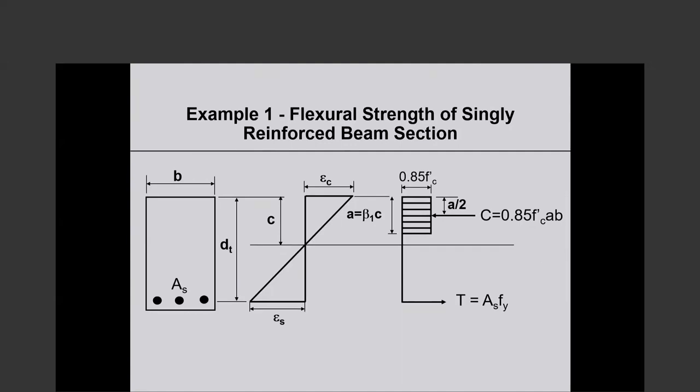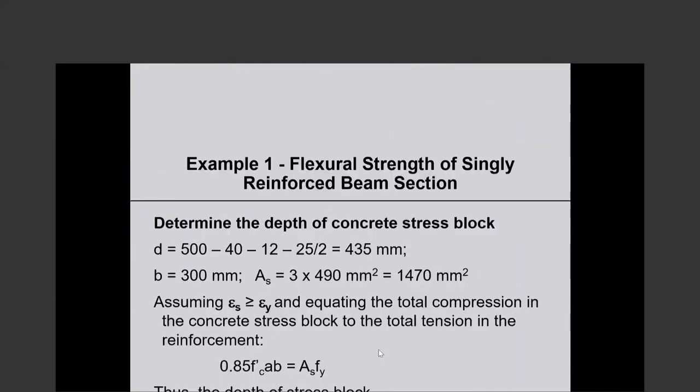We will calculate the flexural strength of this section. It's a singly reinforced beam section, meaning there is no compression reinforcement, only tension reinforcement. Okay, so this is the same picture as before. Nothing to add. The section, the strain distribution, the stress distribution is a rectangular stress block as described earlier.